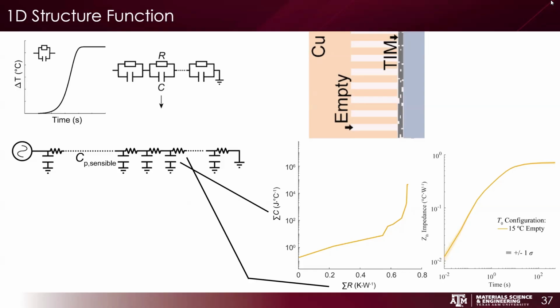If you plot the thermal one-port from the source to the drain, the actual values of this ladder represent the specific capacitive and resistive elements within your thermal network. So these can be mapped physically onto the system. The first slope can correspond geometrically onto the system, and each slope would then be a different layer within the system.